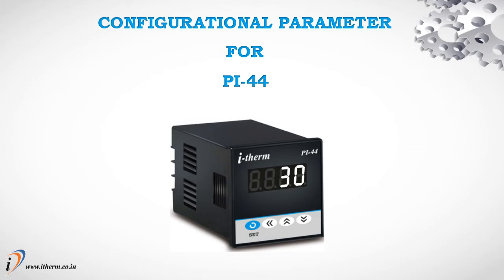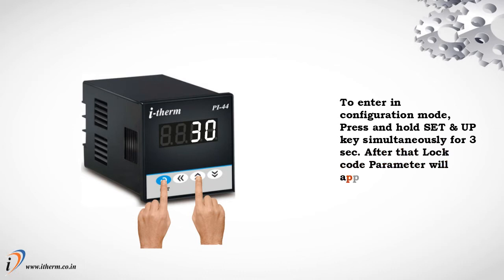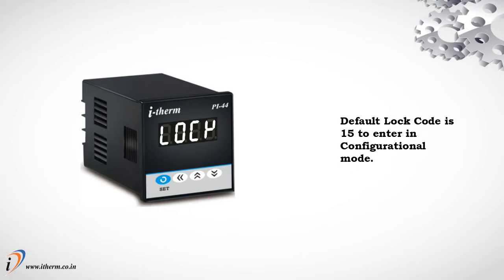Configurational parameter for PI44. To enter in configuration mode, press and hold set and up key simultaneously for 3 seconds. After that, lock code will appear. Default lock code is 15 to enter in configurational mode.